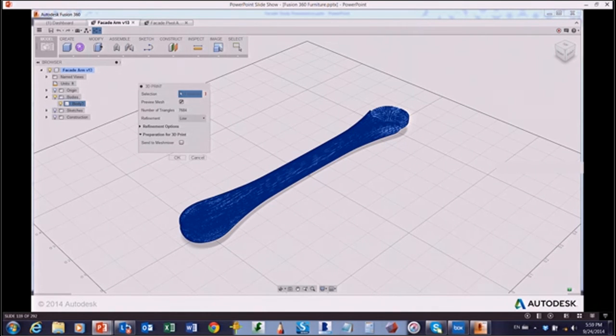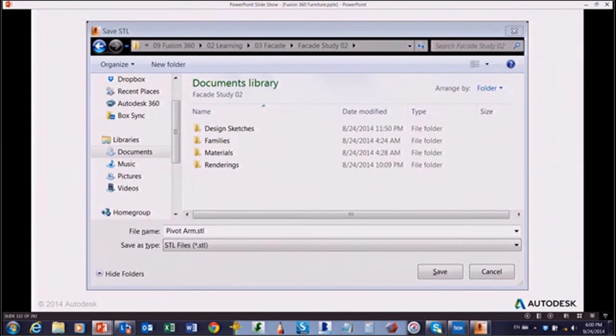That was pre-Fusion 360 days, so I was using some older tools. Looked fine on my screen, but at a really big scale, didn't look so good. So 3D printing and even milling, it's these flat faces, we can do the STL file format. So I can go back and I can change. I can say low resolution, medium resolution, high resolution. It's kind of like image resolution, but in 3 dimensions. You say, okay, you make your STL file.